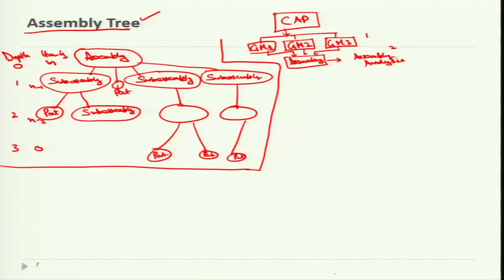So it depends which kind of software we are using, how independent the software is from the other components, or whether the components are related to each other or not. Generally, changing the component dimension at the base level, that is at the basic library level, changes the dimension in the overall assembly itself. That happens in assembly based software. So that is why it is important to have proper assembly planning.